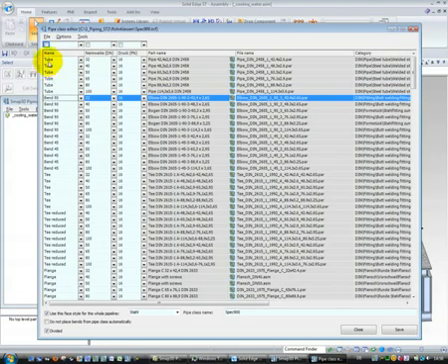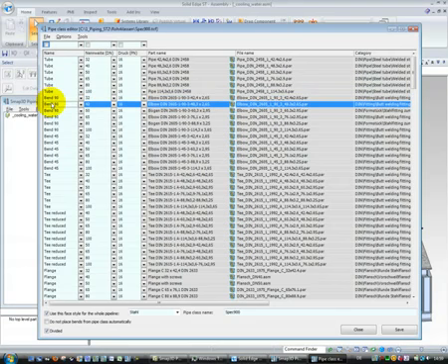These rows are the general definitions, for example, to which standard situation on a pipeline, to the tube or pipe standard situation, to the bend 90, bend 45, T and so on standard situation, and also the definition for which diameter or which pressure it should be used, and also included is the definition which specific 3D model from the 3D library should be used for this defined situation.